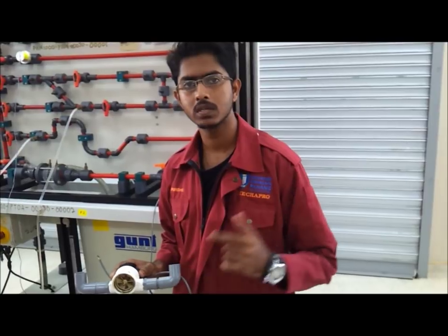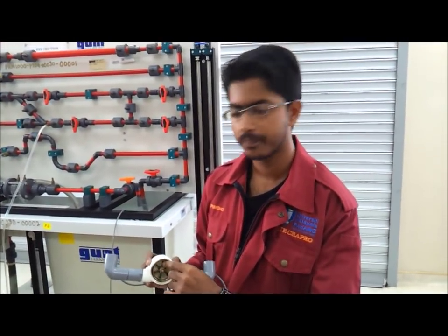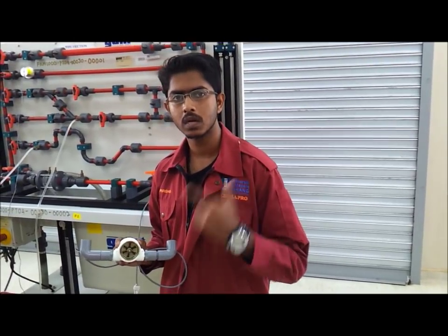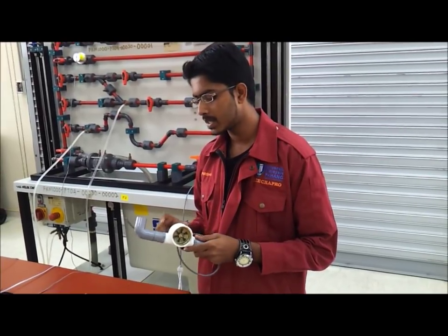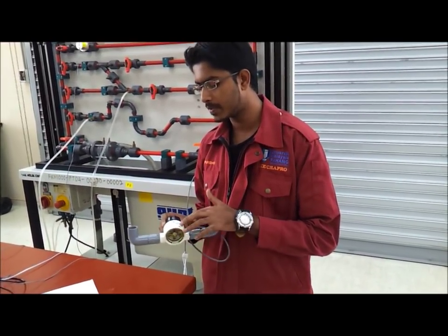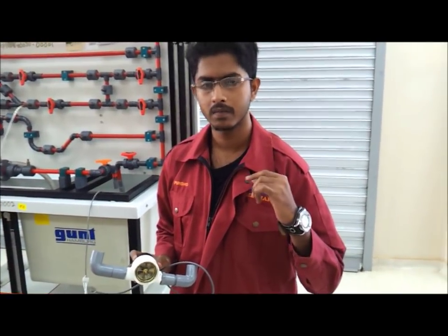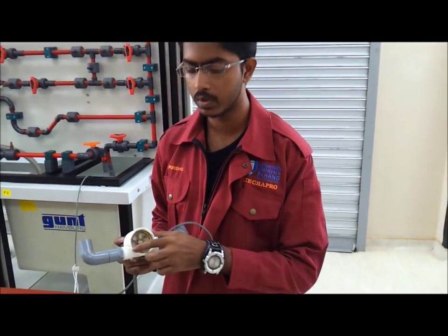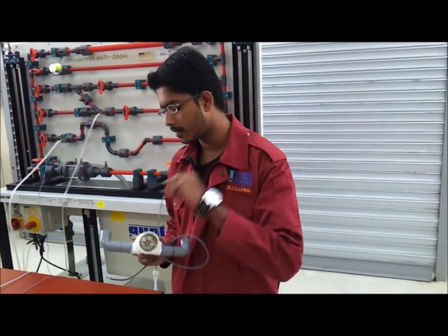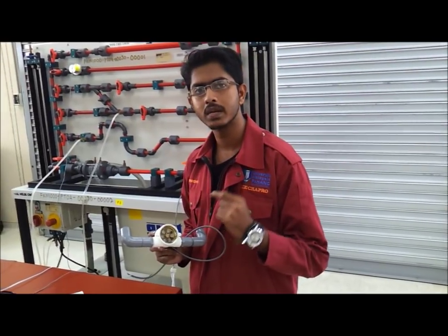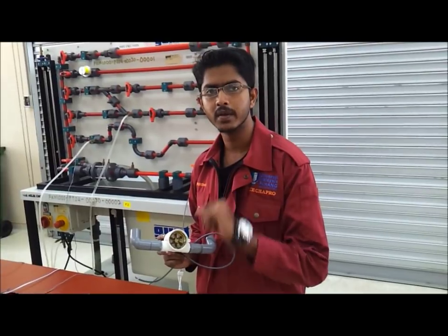As the water starts to flow, it will be trapped in the space between the turbine blade. As more water flows, it will cause the turbine blade to rotate. Beside the turbine blade, there is a transmitter connected, and the transmitter has a sensor that will generate a signal from the rotating blade. The transmitter then changes the signal into an electrical signal that will be displayed on a computer or digital display.